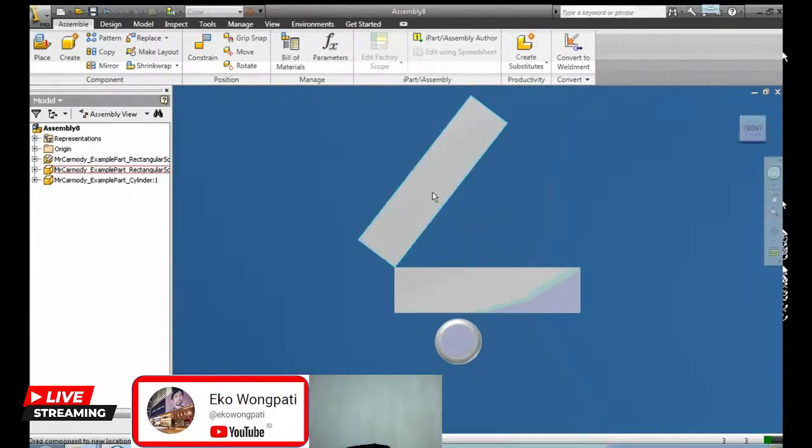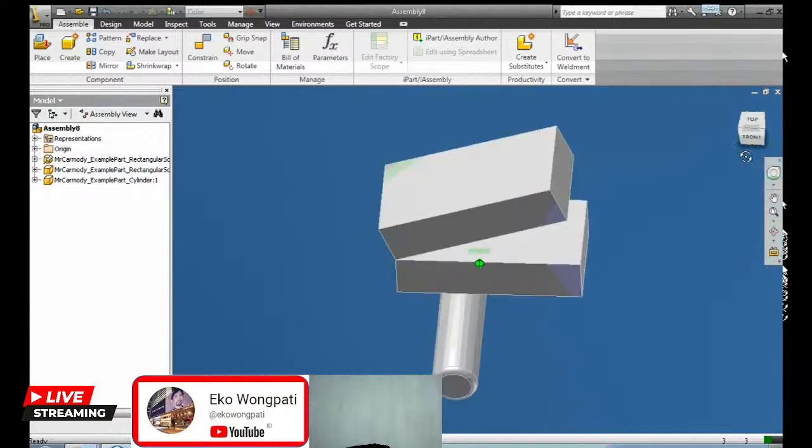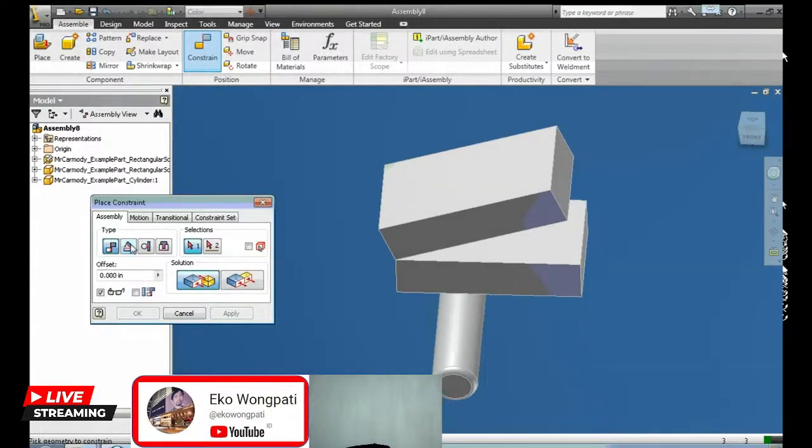The order that I click on the constraints matters. So let's take our degree. If I click the bottom surface first, I'm going to do the two top facing surfaces of my rectangular solid. So I'm going to click the bottom one first, and then the second. And I'm going to set it to a 45-degree angle. And you'll see what happens in the example.